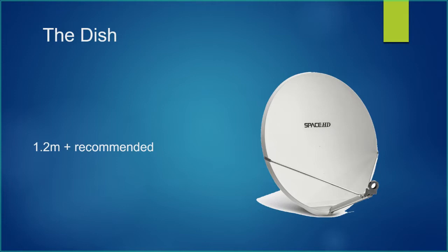So if you're planning on setting up an OSCAR100 station, based on the talks today, and DATV is something you'd be interested in, it might be worth just immediately going for a bigger dish. If you're planning on transmitting on the DATV, then you'd actually want to go even bigger than that. I'm currently using a 1.8 meter dish for all my transmissions there.